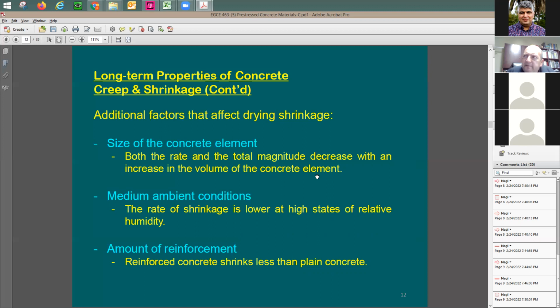Would you compare here a pre-stressed beam in California and, let's say, in Arizona? I'm not talking here about the aggregate, because of course the aggregate is going to be completely different. Concrete mix design here is going to be different than there. But I'm just saying, if you have the exact same beam and you put it to dry here in California and you put it to dry in Arizona, which conditions do you think that you're going to have more shrinkage? Is it here in Arizona?